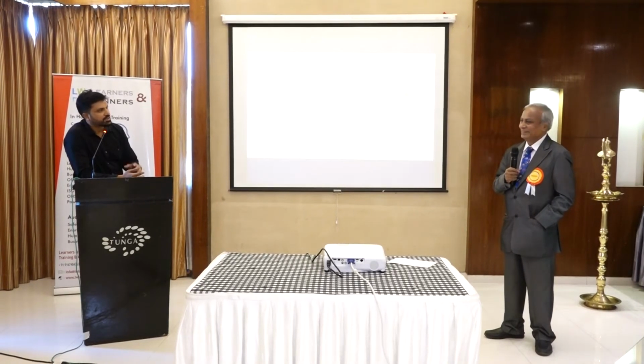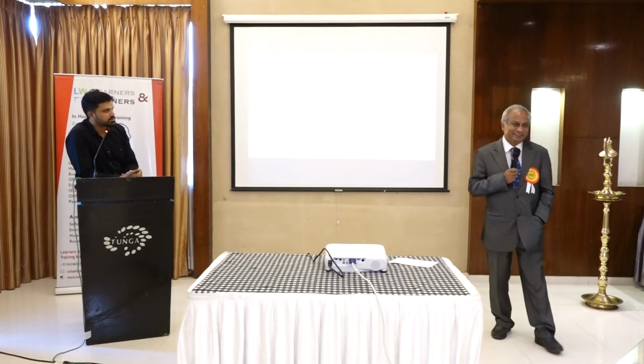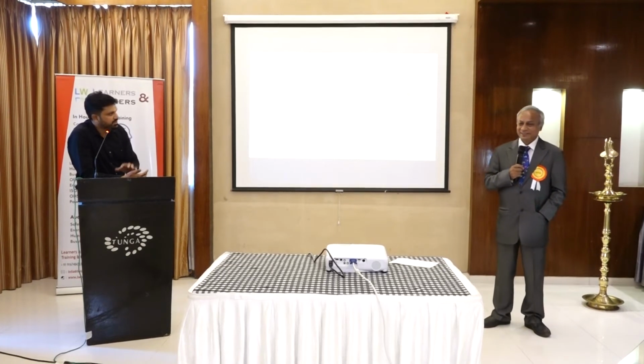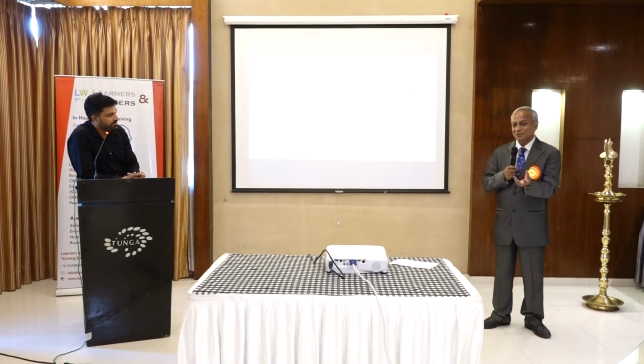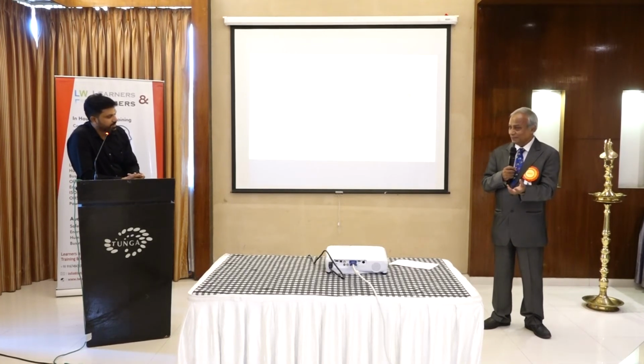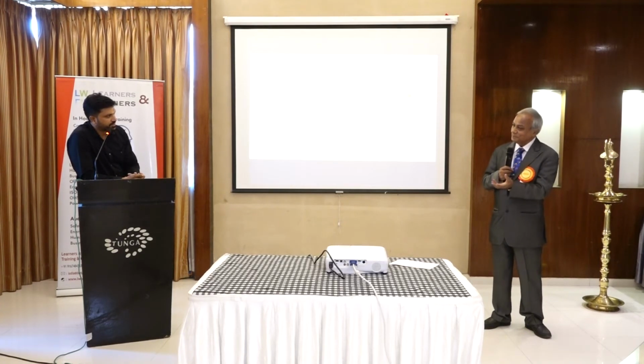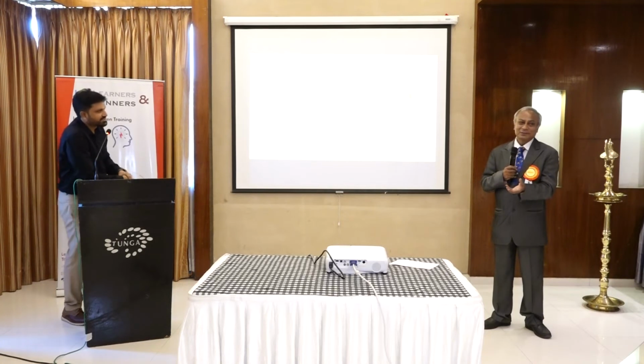Still, we face this during monsoon seasons, when there is a sudden temperature difference. But when there is no moisture, condensation will not come. If it is totally moisture free, because of putting in silica gel, then condensation will not come. Very simple solution.